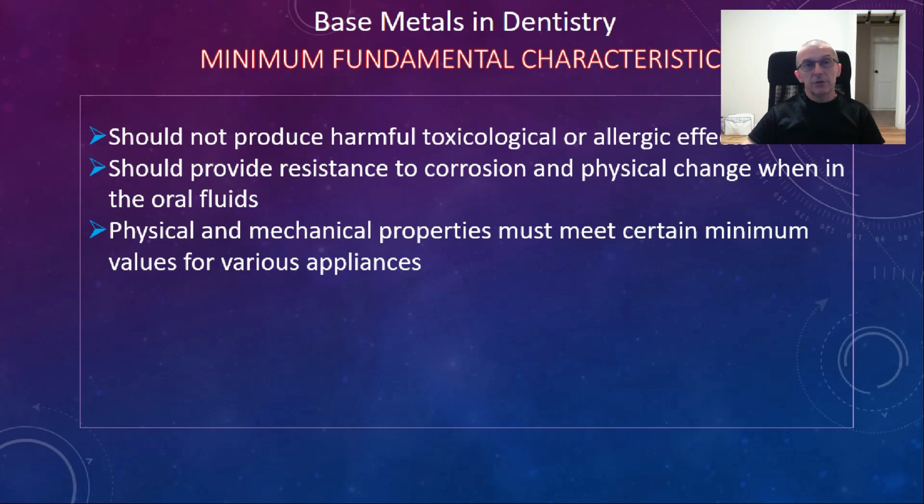We also have to make sure that during heating it produces as little oxides as possible. Although for porcelain fused to metal we may need some oxide, because some oxide promotes the bond of porcelain to the metal. We have to know properties like coefficient of thermal expansion, so that we can actually match it up with the porcelain. Mismatching coefficients of thermal expansion will crack the porcelain during firing.